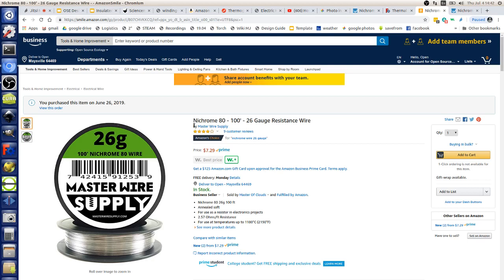So that's great, because if you're running this machine, the 3D printer, 24/7 for a whole year, you're saving about $30 of electricity, so this pays for itself in less than a year. It's worthwhile doing an insulated bed. I don't think a lot of people do that. I don't think the energy consciousness is so much in there right now for this.